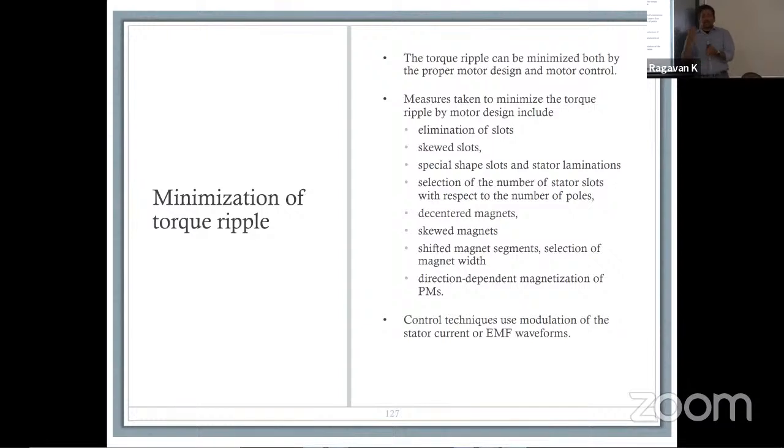essentially what you're doing is you're trying to figure out what your resonant frequency is, and you're trying to change the design or the structure so that you don't hit them. So it's not a black box approach. You are trying to be very strategic in how you are going to make this not be noisy. If you know what frequencies are going to be most problematic, eliminate those.